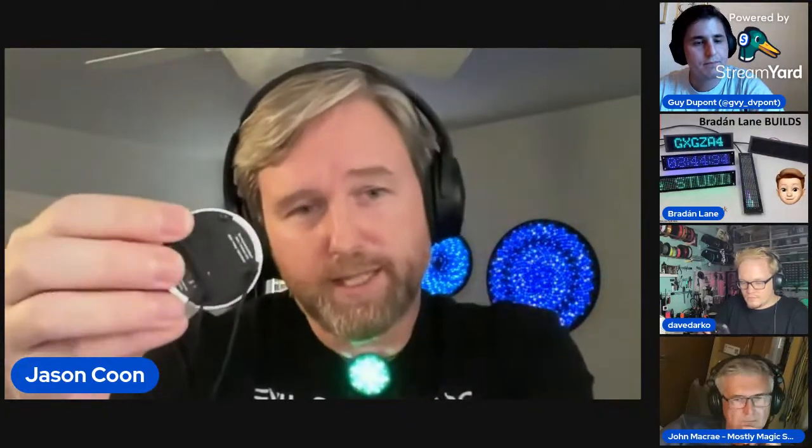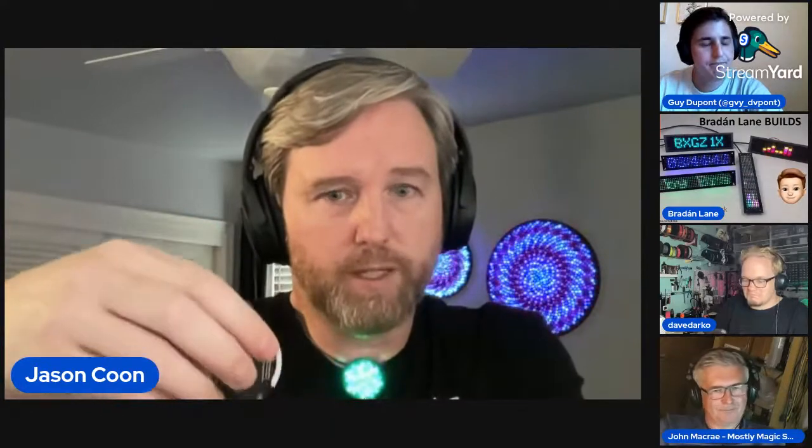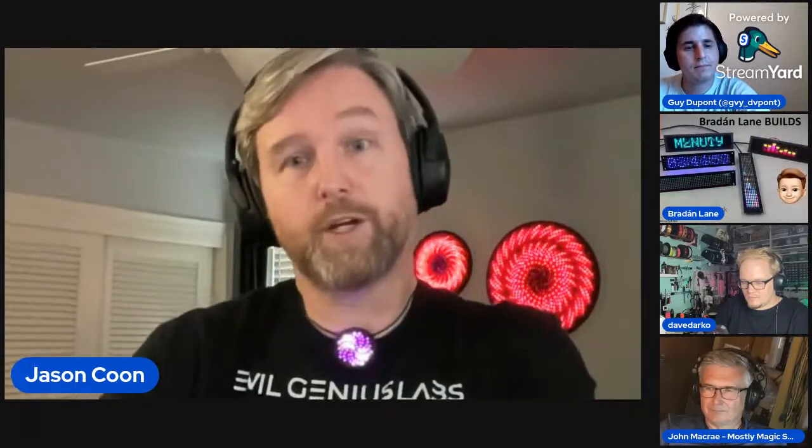Ben Electromage brought the Pixelblaze, which is behind this 3D printed cover on the back. It's a controller that has an ESP32, and it hosts its own web UI on the ESP32 over Wi-Fi. You can either get it connected to your Wi-Fi, or it can host its own Wi-Fi network. You connect to it with your web browser on your phone or laptop, and it presents a web UI where you can choose different patterns. You can arrange those patterns into playlists, and then you can even interactively write code for your own patterns.